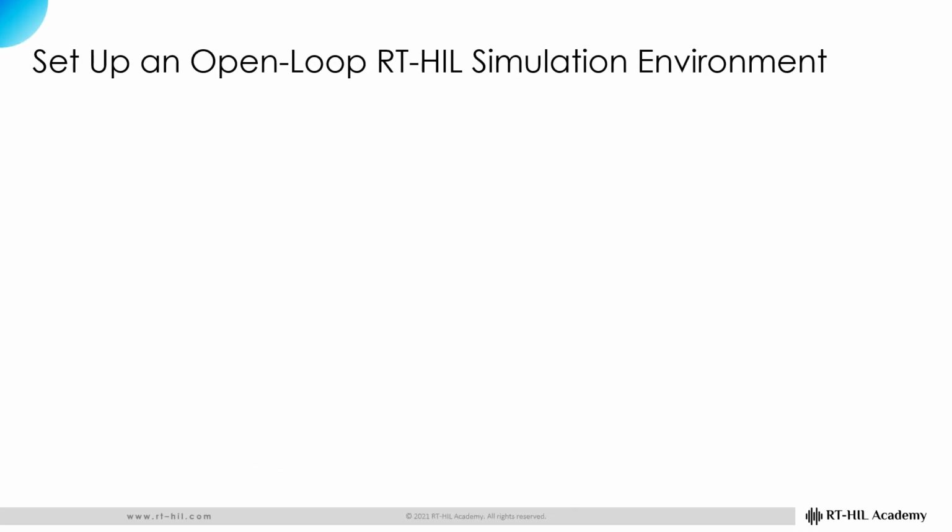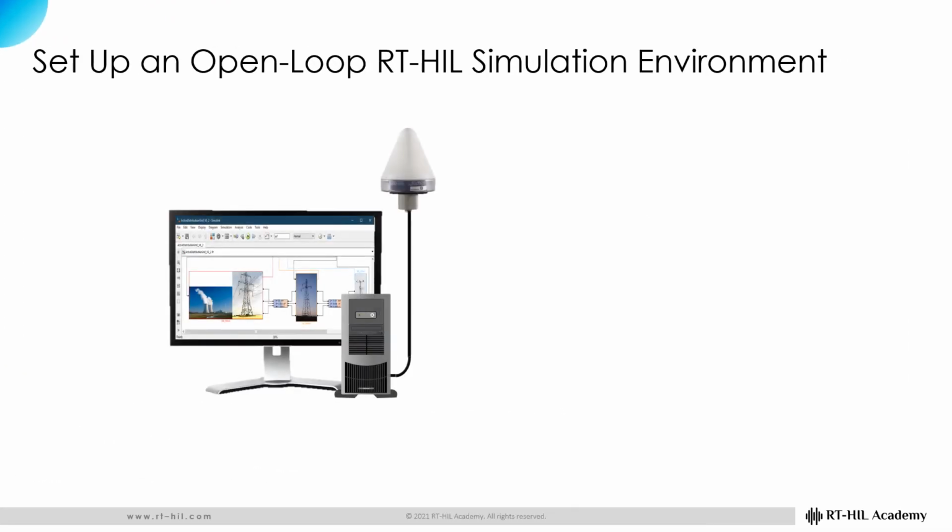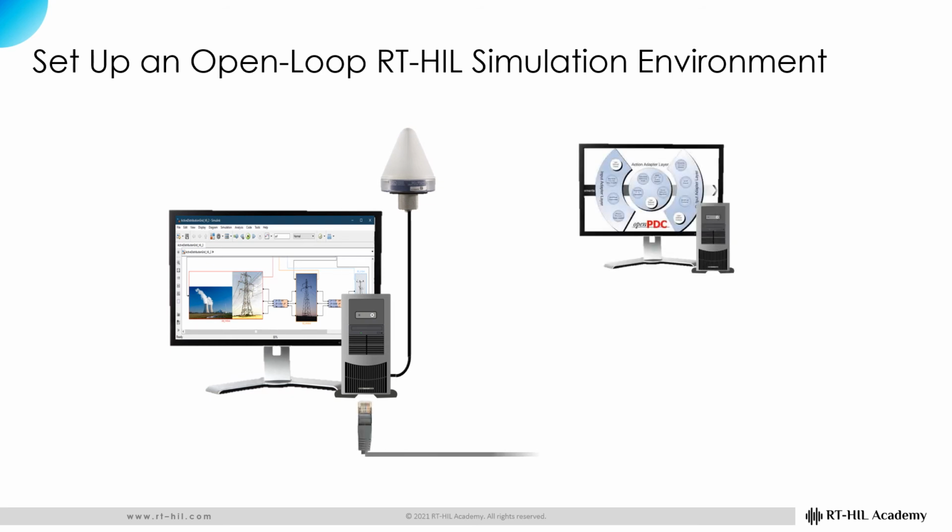Okay, now that you know real-time simulators can be configured to act as PMUs, and you're familiar with PMU clients, you can set up an open-loop RT HIL simulation environment by use of IEEE C37.118.2 protocol.